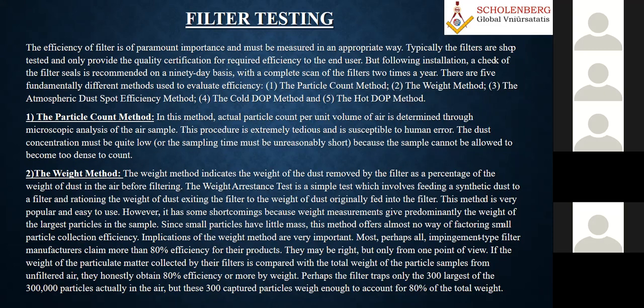As I told you, the efficiency of the filter is very important, and it has to be measured in an appropriate way. Typically, the filters are shop tested and only provide the quality certification for the required efficiency to the end user. You should insist on the test certificates. Majority of the time, people in the market don't bother. They don't even ask for that, or you don't specify it in your specification. If you don't specify, the contractors will always take undue advantage of that, and then they will go for any type, because manufacturing of filters is not rocket technology. So people can do that. But if you want to maintain the quality, you want to maintain the standard, then you have to go for a test certificate.